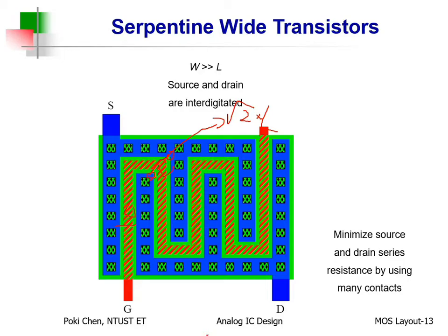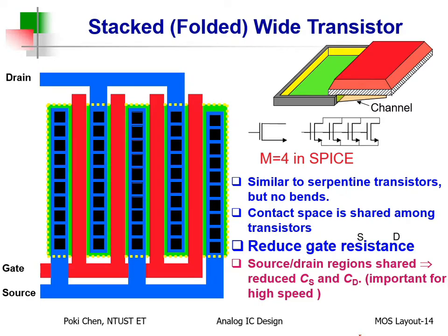Anyway, after such kind of layout, you can only estimate the W and the L, but without too much accuracy. Alright? So I wouldn't like you to be trapped in such kind of trouble. So I still wouldn't like to recommend you to do such kind of layout. But what else can we do? That is the simplest one. I would like to recommend you stacked layout.